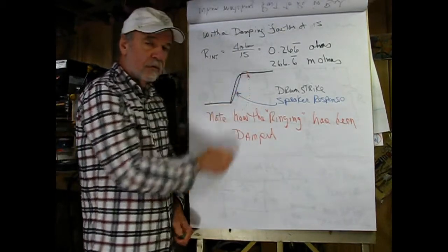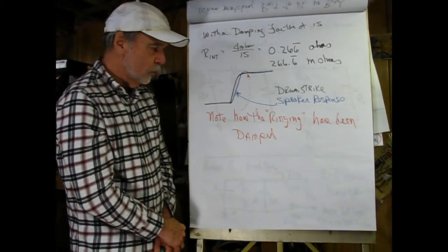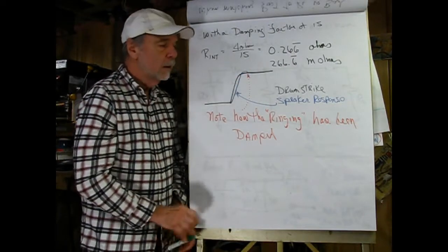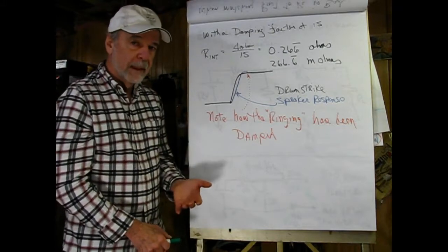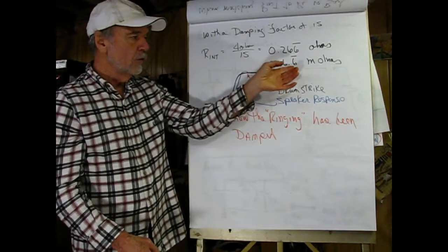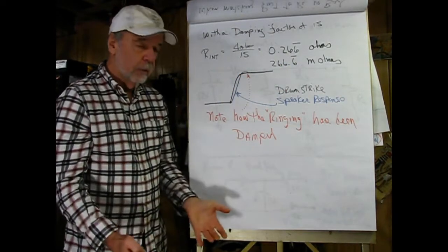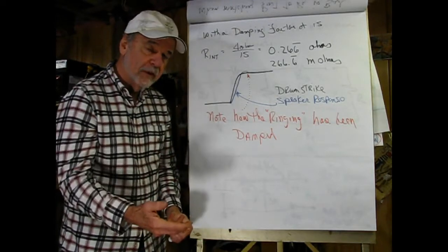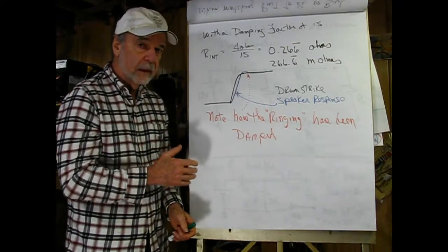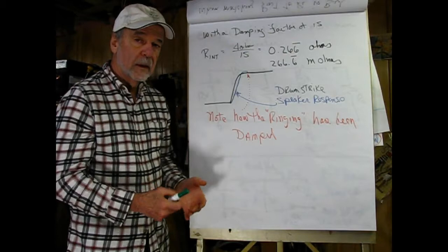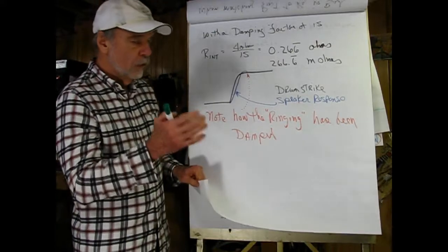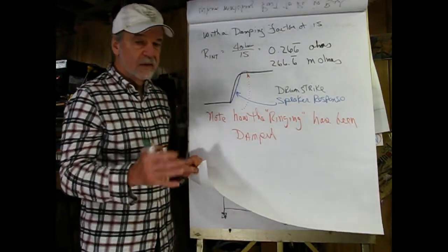As you can see, it settles very quickly. Thus, there's much less distortion. And we would say the ringing, which we had those little cycles up there, would be damped. So that's an example where you don't want to match. And suppose you connected a bunch of speakers in parallel that equaled 266.6 repeating milliohms. Theoretically, you'd get a ton more power out of it, but the protection circuit on the amplifier should shut it down. It wasn't designed to deliver that kind of power, and if the protection circuit didn't work, you'd blow up the amplifier. You'd be replacing transistors and possibly power supply components. So, in summary here, there's a time you want to match and a time you do not want to match.